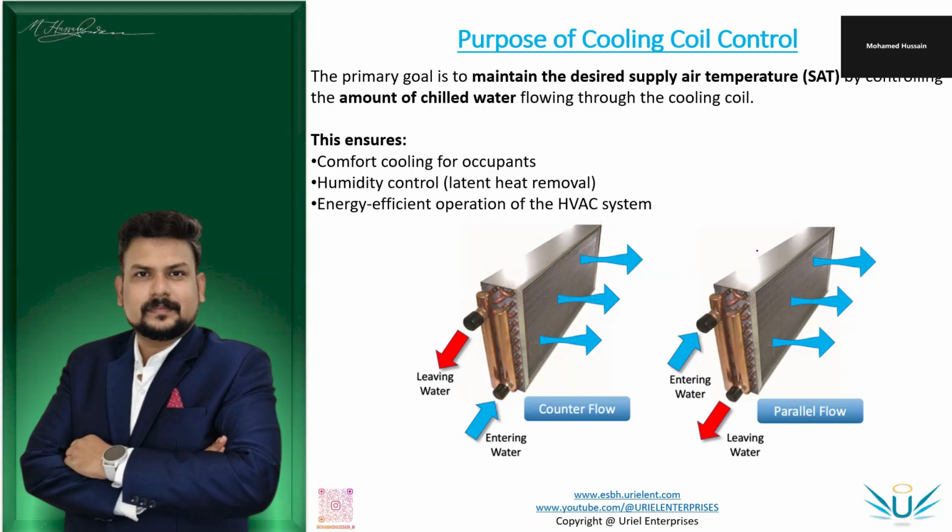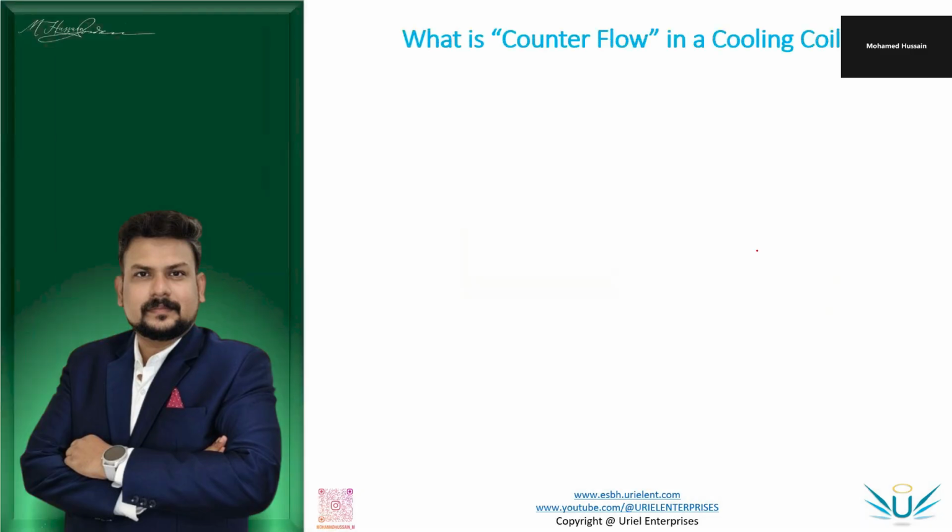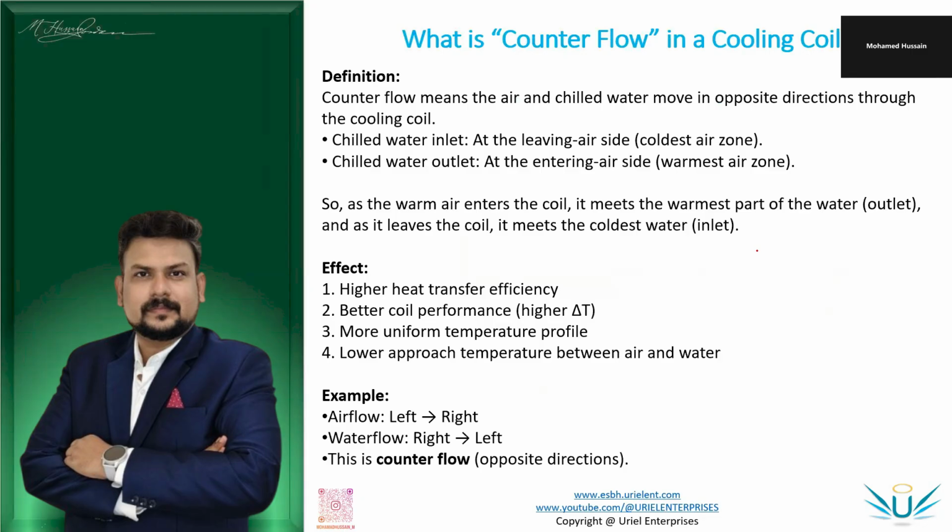Now we want to understand the valve placement. The cooling coil has an entry and an exit. Before the cooling coil, we will place the valve. How will we size that valve first, and how will it be placed? Will we place it on the supply side, which means the entering water side, or the leaving water side? This question will come. Before going to that explanation, let me give the descriptions and everything. You can take notes of whatever I explained in the previous slide. That definition is given here.